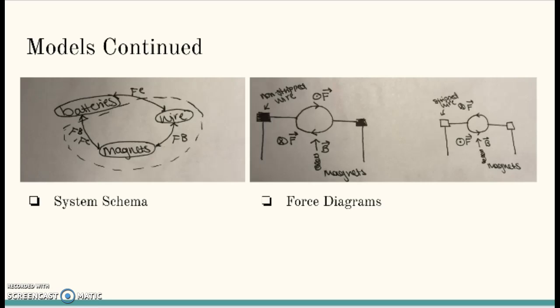If both wires were stripped completely, the loop would have spun because there would have been no current running through it, but it would have made only half a rotation before changing directions, because the permanent magnet repels both the north and south poles of the wire loop. By stripping half of the wire, the current is turned off for a portion of a rotation when one pole nears a magnet. The momentum from the previous rotation keeps the loop moving, and the force of the magnet on the far pole of the wire, north or south, takes over again, keeping it turning.